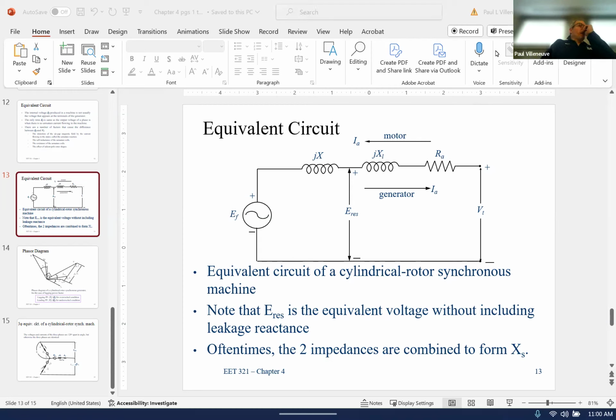I worked on a project, it's been a couple years, in New Hampshire where they were putting in a 50 MVA synchronous condenser at a substation called Huckins Hill. The idea is that with all this DG, distributed generation or distributed energy resources, you don't have really strong systems in terms of being able to provide fault current. When a fault occurs on a system, these synchronous condensers can help maintain the system grid, meaning the voltage, and then you can actually detect the fault. So the synchronous condenser is really there just for fault analysis.